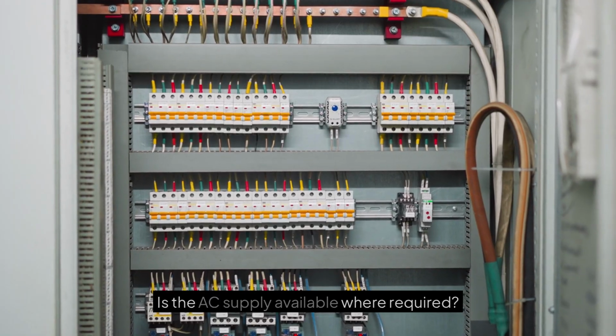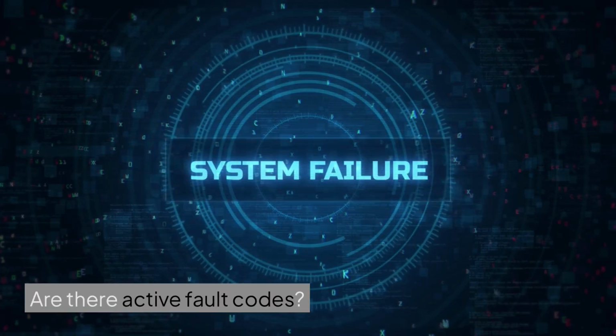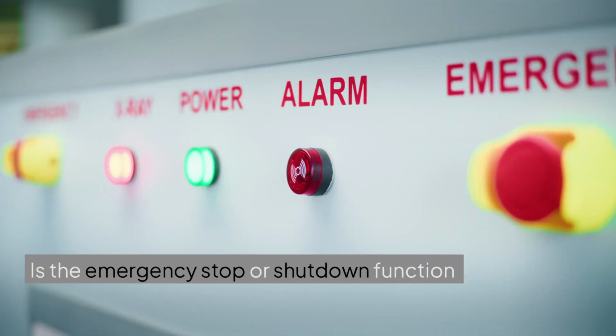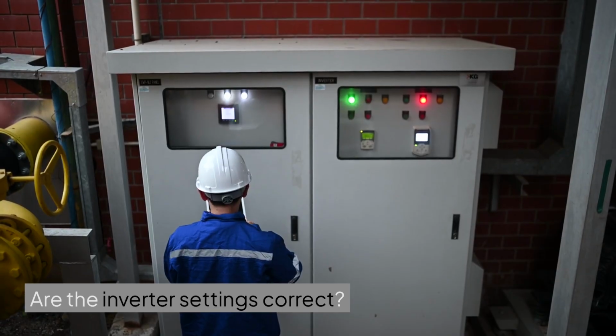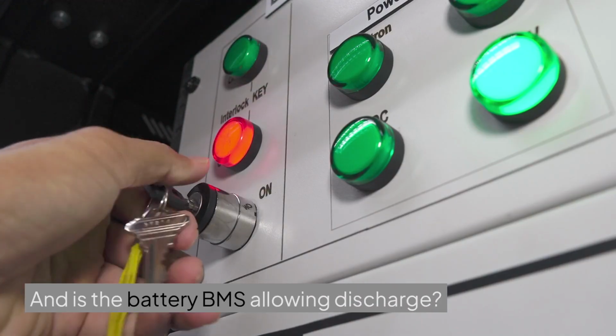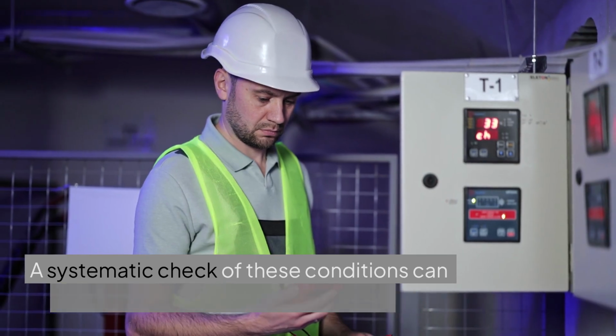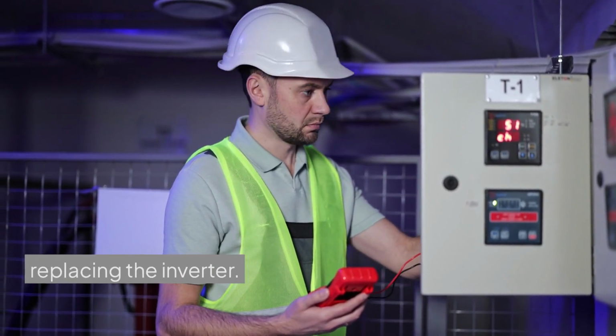Is the AC supply available where required? Are there active fault codes? Is the emergency stop or shutdown function activated? Are the inverter settings correct? And is the battery BMS allowing discharge? A systematic check of these conditions can often identify the problem without replacing the inverter.